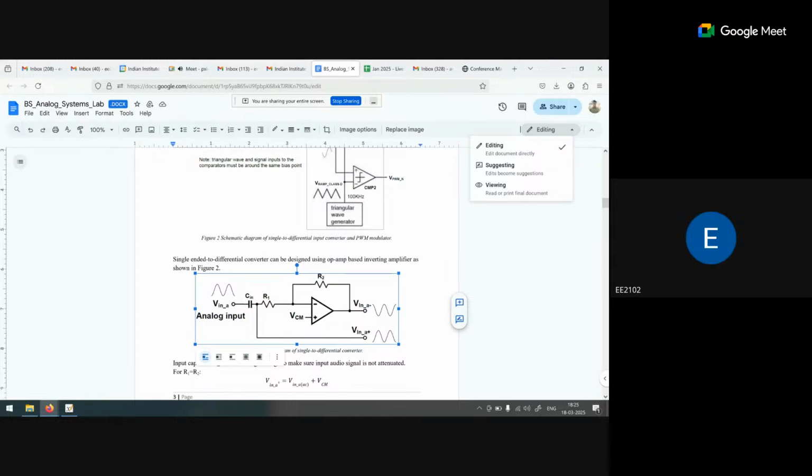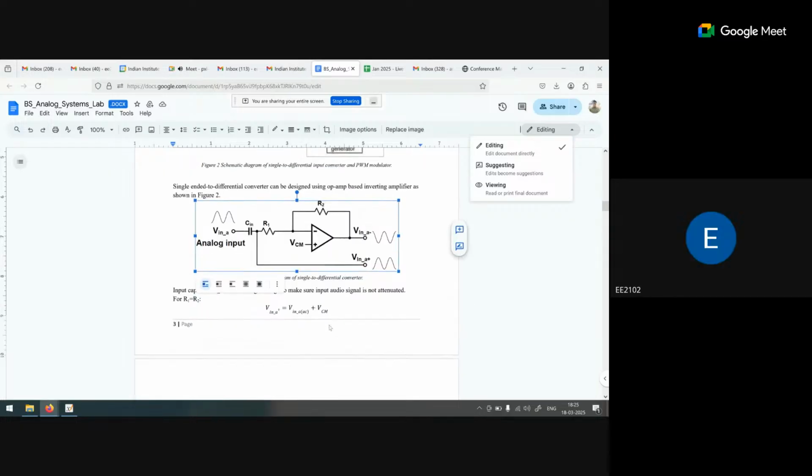Basically, the electrolytic capacitor is required to store charge. For that purpose we require the electrolytic capacitor, and where we need to provide high impedance, we generally use ceramic capacitors. Ceramic capacitors are generally in the nanofarad range, and electrolytic capacitors are mostly in the microfarad range. Okay, sir.